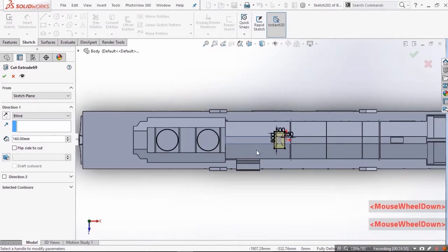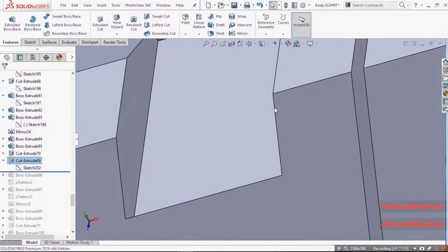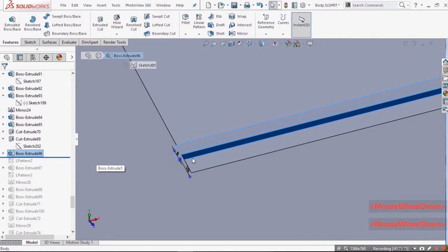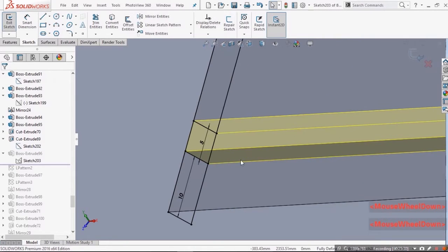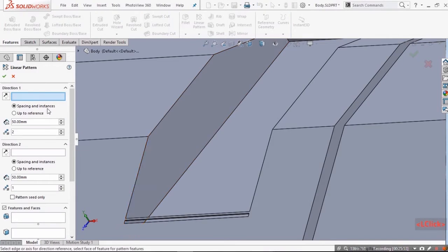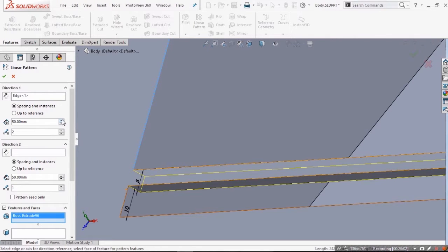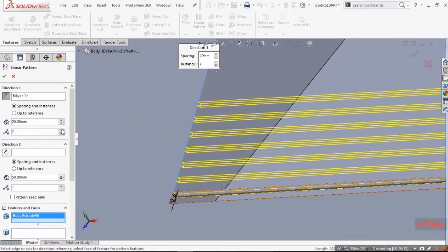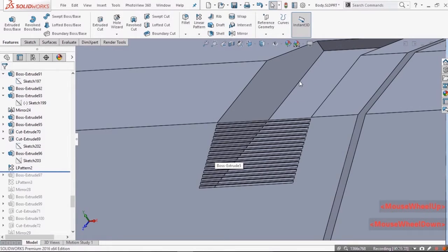You can notice here what sketch surface I have selected to draw here, the uppermost one. Again, here I will be using linear pattern. Just pay attention and see how it would work. You have to mention the pattern direction and the feature. And then the counts, how many times you want to pattern the given feature. Here you can see that we can't exceed more than this number.